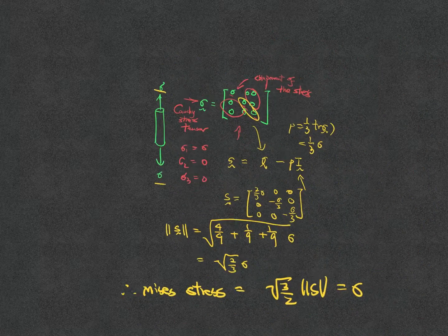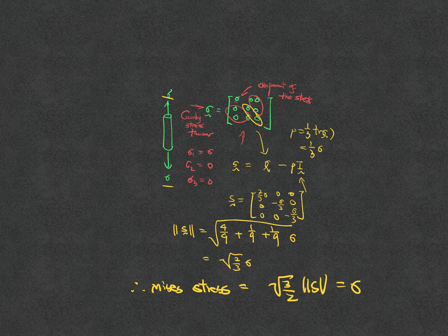Okay, so this actually makes it very convenient, because if I have a uniaxial tensile test, I just load the material all the way until I start to see the plastic deformations, and then I put this measurement into an Excel file or into a record. And then I can use this to compute the J2, and hence I can detect the onset of the plastic deformations by using a very simple device, the uniaxial tensile test. Okay, I don't even need to directly shear the material, which is actually harder.